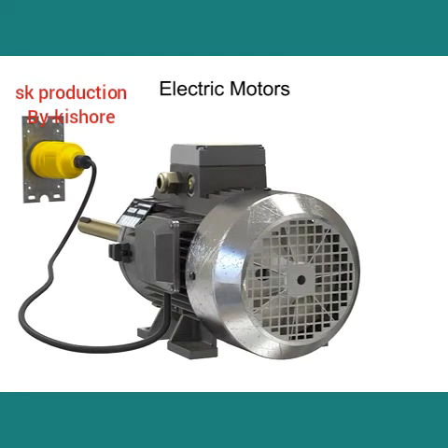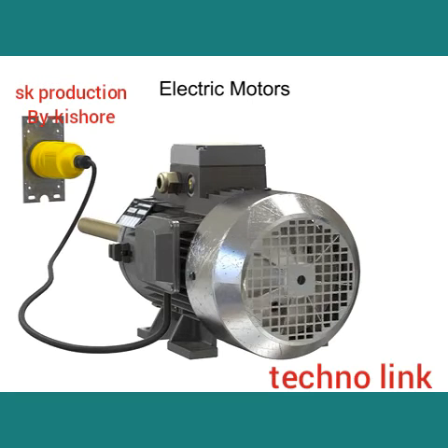Since these multi-directional motors are equally efficient in either direction, there's no standard direction of rotation. Therefore, when a three-phase motor is first connected, it may run in either direction, and technicians must be careful to install it properly. While the motor itself can run in either direction without harm, the components that the motor drives